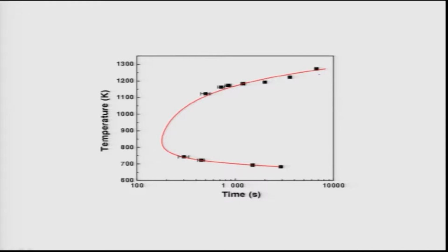Remember the temperature scale is a little bit odd here. If I add 727 plus 327, this becomes 1054 degrees Celsius, but it is showing something higher here. So let us put this as 1000, this as the A1 temperature, and remove this temperature because it will be confusing to you.